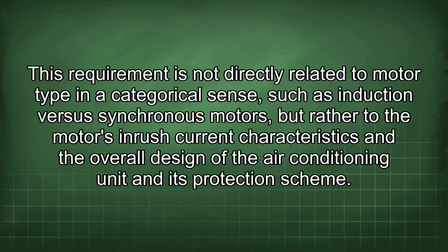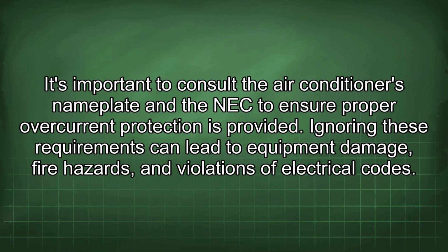This requirement is not directly related to motor type in a categorical sense, such as induction versus synchronous motors, but rather to the motor's inrush current characteristics and the overall design of the air conditioning unit and its protection scheme. It's important to consult the air conditioner's nameplate and the NEC to ensure proper overcurrent protection is provided. Ignoring these requirements can lead to equipment damage, fire hazards, and violations of electrical codes.